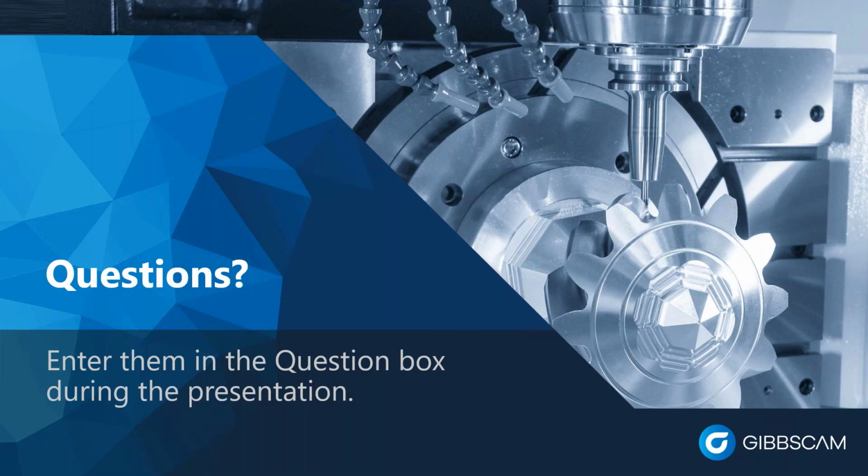Absolutely, yeah, you can. In the tool axis control, you can put a lead on the tool, and I didn't really display that. It would have been suitable perhaps in the first toolpath option I created, and that way you're not machining at the tip of the tool, but by rotating the axis of the tool relative to the surface you're cutting, then you're cutting out on the radius of the ball or your end mill, and thus getting better surface footage. Right. Agreed.